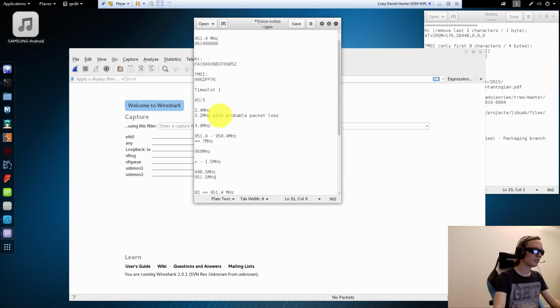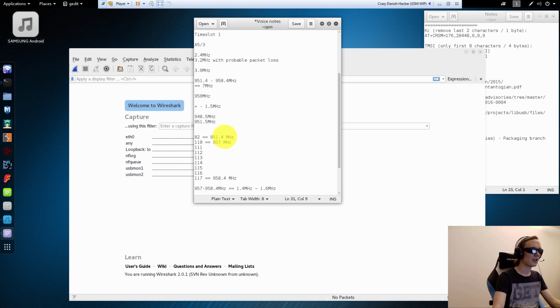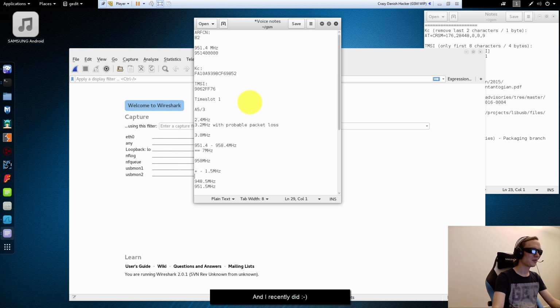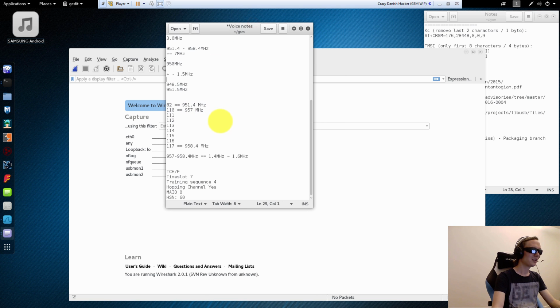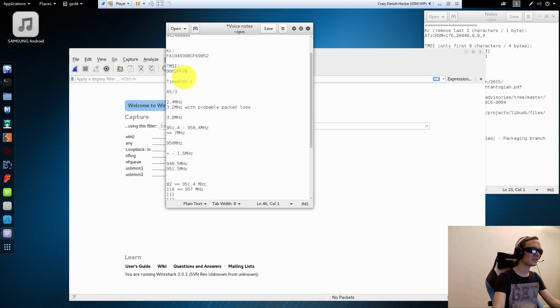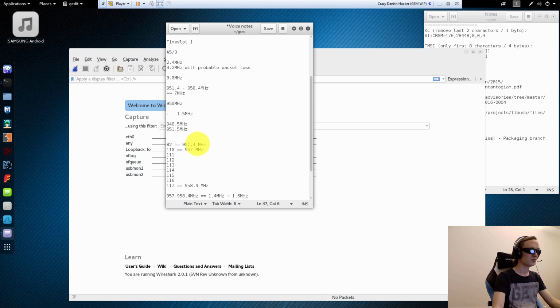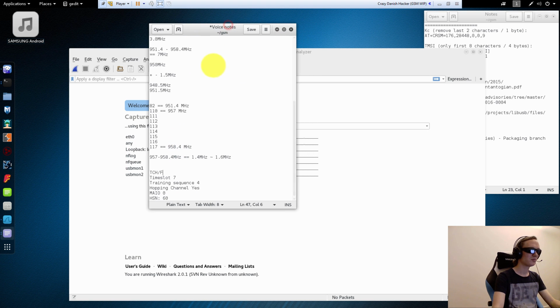So as you can see, in this case, we need something like a BladeRF or a USRP, or we could do with less, but basically I need to buy a better software-defined radio to capture myself talking on the phone, if channel hopping is on, of course. So that's a major issue, even though there are programs to decode both the SDCCH hopping and even the TCHF hopping as well. So that's what I'm going to try and do in the future. But for now, I won't be able to decode my own voice call.